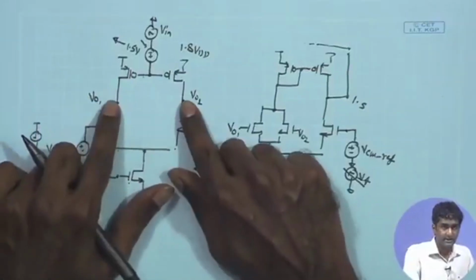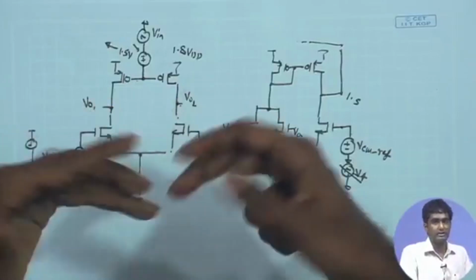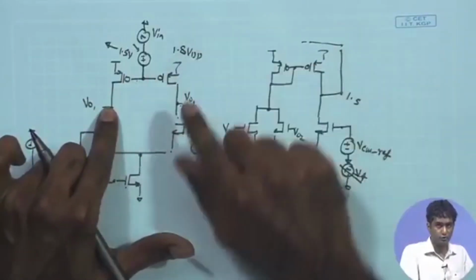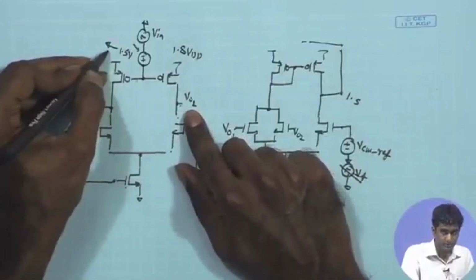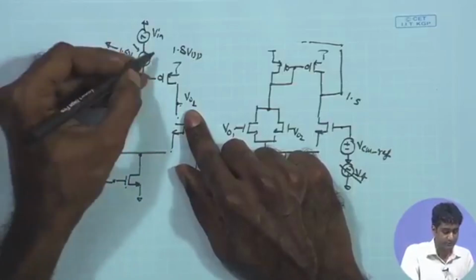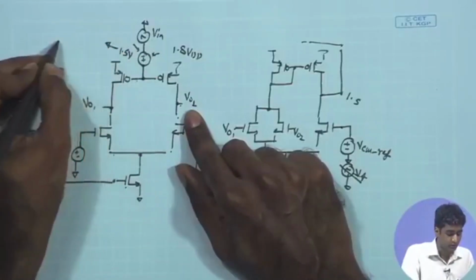But if it is not coming exactly and you want to be more precise about the DC bias point and make sure that in the open loop condition this DC bias remains the same or very close to the previous one, you can sweep this DC potential. So, in the simulation analysis you have the option of DC sweep.